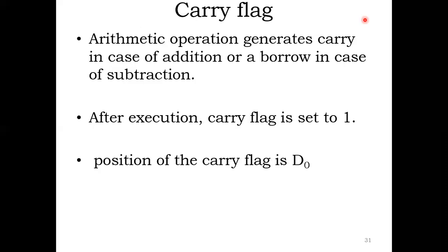Carry flag. Arithmetic operations generate a carry in case of addition or a borrow in case of subtraction, which means after execution the carry flag is set to 1. The position of the carry flag is D0.